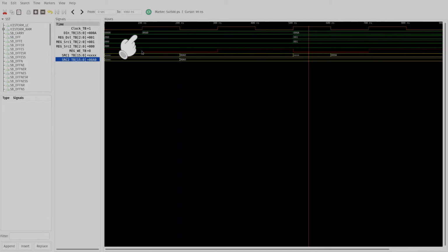So there the write enable goes low because we are writing. And then on the negative edge is when the action takes place. And here is the output of that register. We know that the output is continuously assigned. It's immediately available on the output as a reflection of the destination, source 1 and source 2. And remember, we set source 1 to 0.